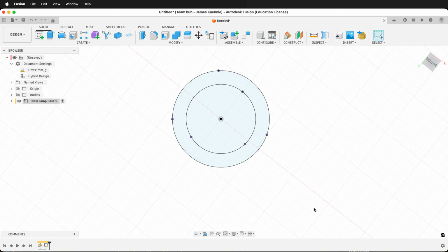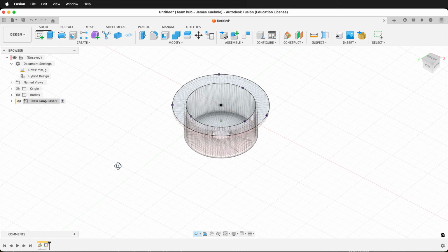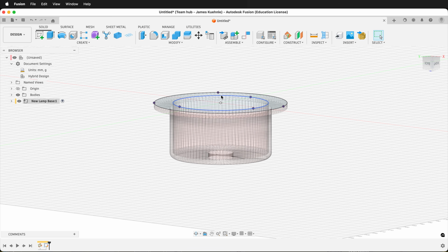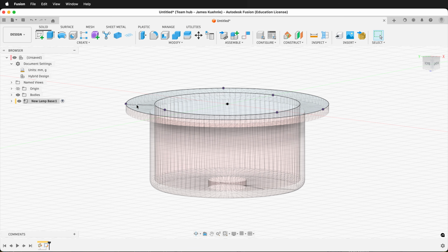Then we can finish our sketch. If I bring the body back, now I have a perfect circle on the bottom of this STL file. But I need to know how much to extrude. I could eyeball it, or I could accurately calculate where it needs to go to.